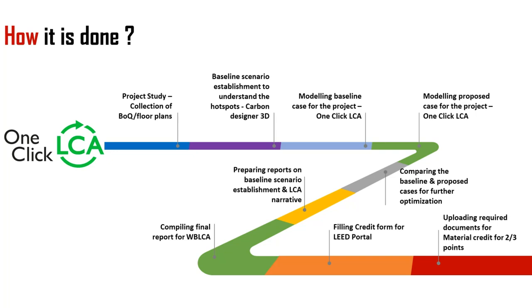This is that workflow. So first step is project study and collection of BOQ or floor plans. Then the baseline scenario establishment has to be done, so as to understand the initial threshold or benchmark of carbon footprint per gross floor area in that particular region.